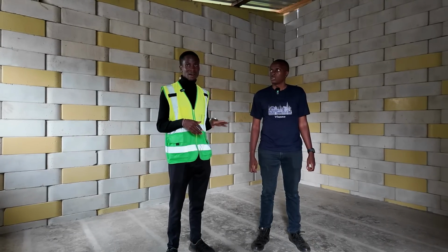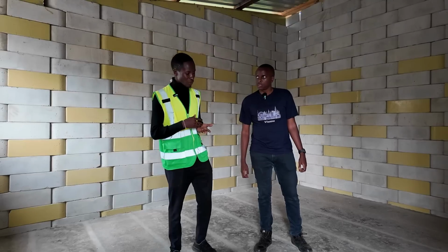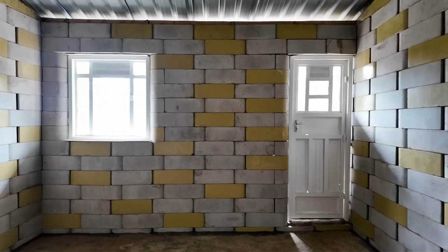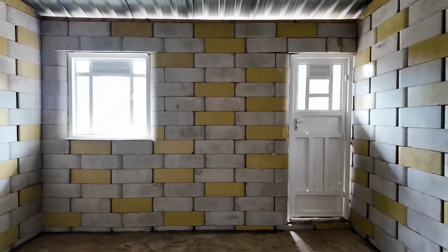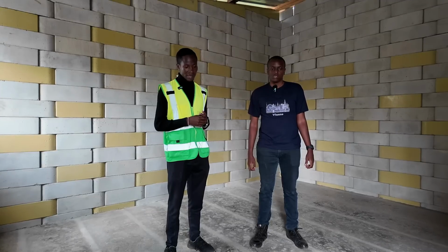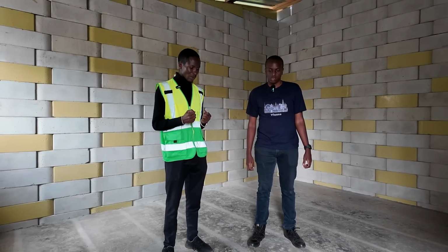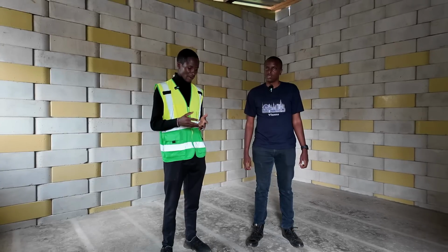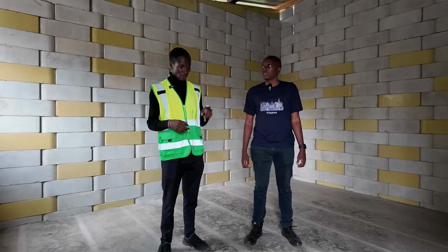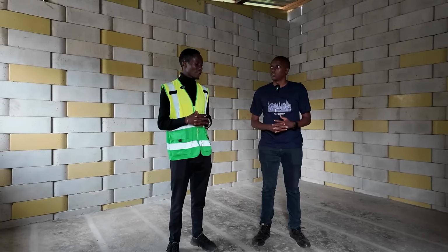That formwork was rather iron sheets from below, and then we put some mesh wire, A92, that is like BRC, but it's the simple mesh that you always see. And then we did a simple concrete atop of it that is mixed with fiber and wood glue. Wood glue has that bonding property, and the fiber ensures that the slab does not crack. So in both of the floors, we have fiber in the concrete so that the concrete itself does not crack.